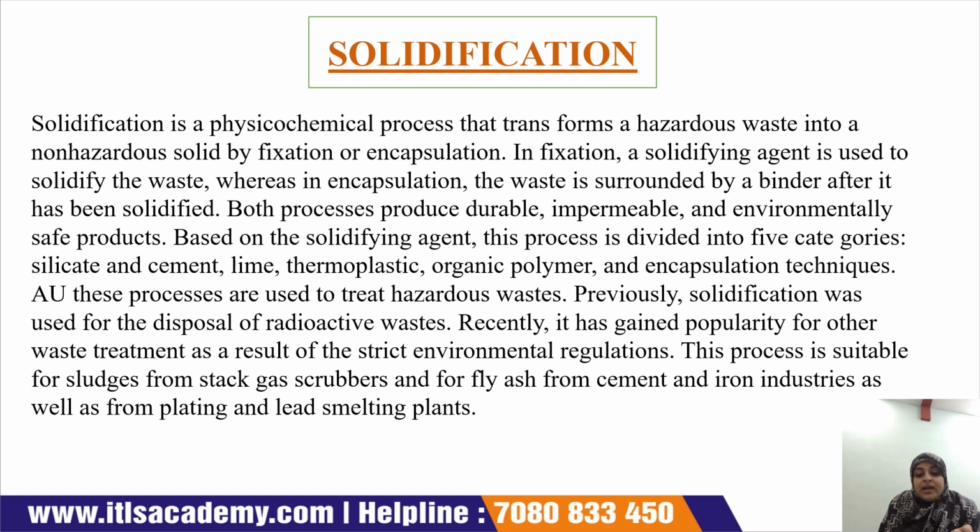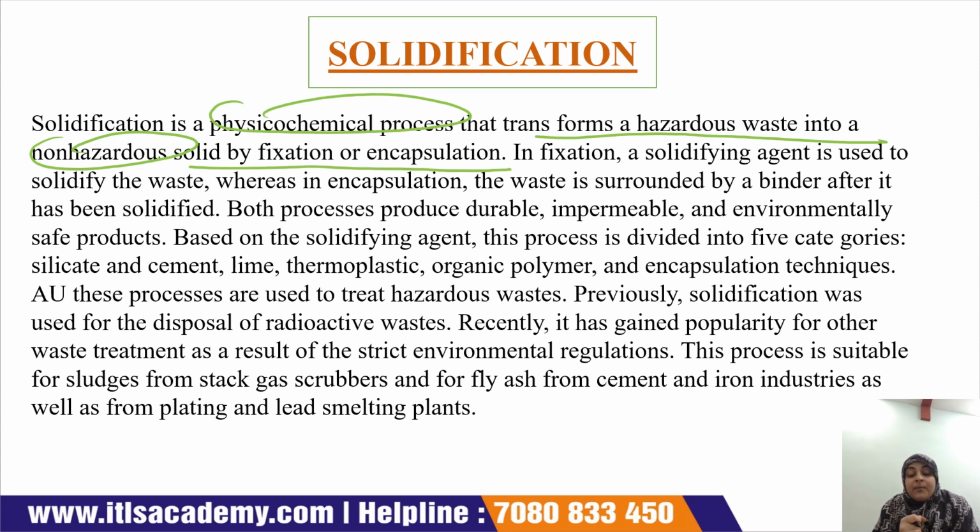Now the next is solidification. The solidification method is a physicochemical process that transforms hazardous waste into non-hazardous waste by solidification, by fixation or encapsulation. Okay, so the main aim of solidification is what? The conversion of hazardous waste into non-hazardous waste by fixation or encapsulation. In fixation, solidifying agents are used to solidify the waste, whereas in encapsulation the waste is surrounded by a binder after it has been solidified.